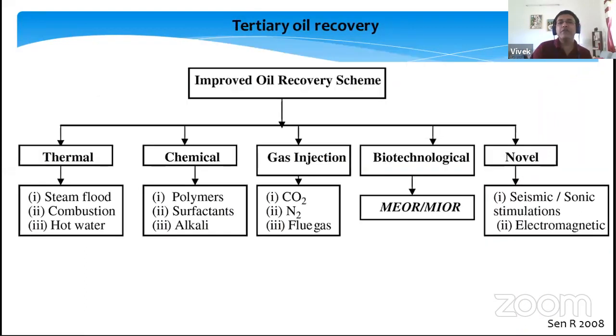And so when both these recovery options meet their demand, when they serve their purpose, we still have a remnant oil of about, say, 50%. This becomes very difficult because this oil, unlike the oil recovered in the previous recovery stages, primary and secondary, is tightly held by capillary forces. So you will find that below the earth's surface a huge amount of oil is still trapped, despite the secondary recovery option, which can only be driven out with the help of tertiary recovery options.